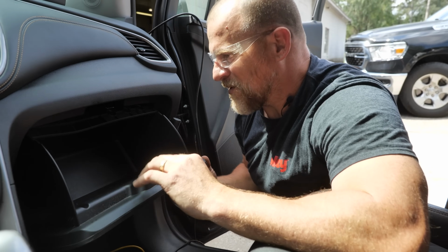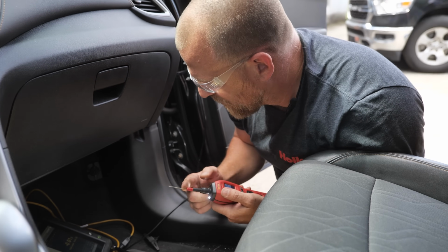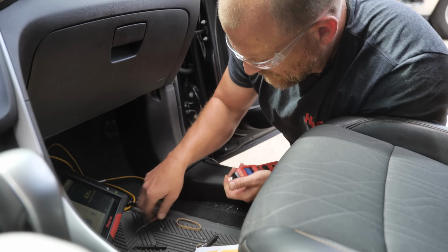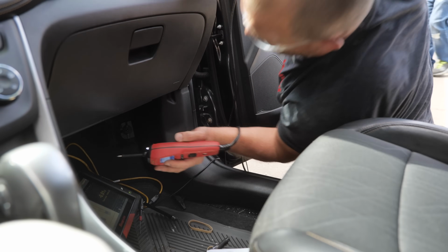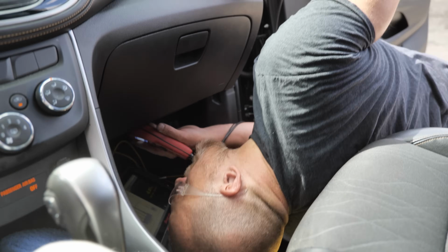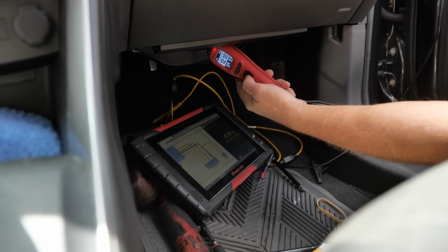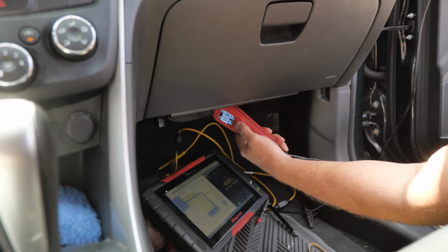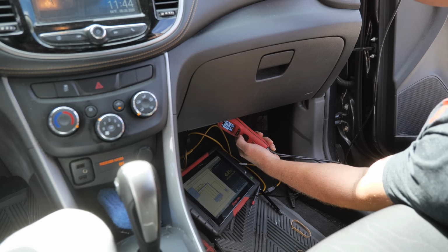We're gonna ground this blower motor. I don't really like this as my ground, the pin, because of current flow. So I'm gonna switch this out. Let's see if I can get on the blower ground wire. Yes. And then ground it. And then what I want to do is go here.